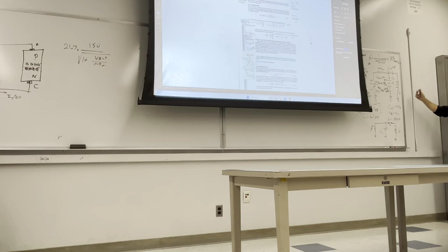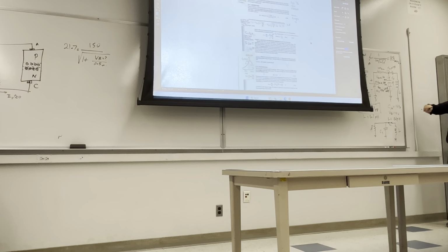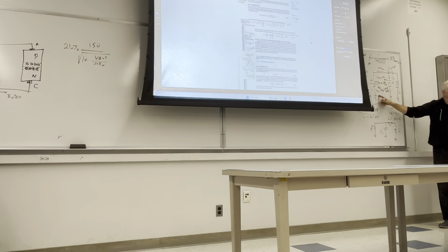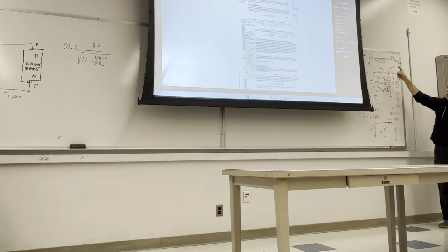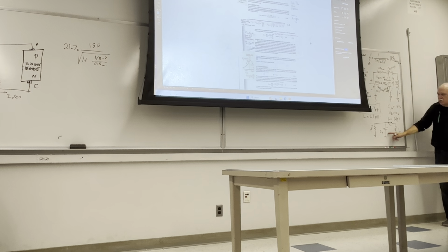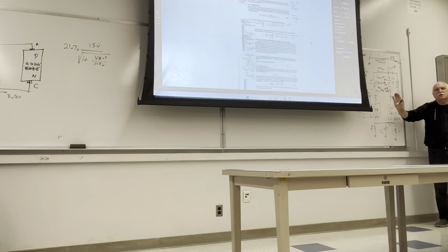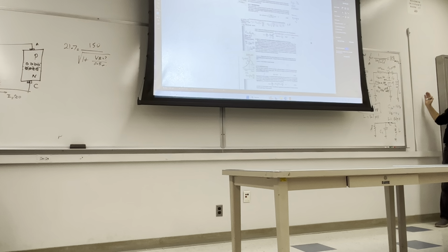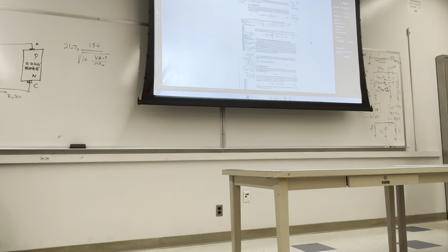We will therefore be able to scan easily, even beyond the FM radio bands, by changing this voltage anywhere from 0 all the way up to 23 volt. Then your resonant circuit will resonate between 88 megahertz all the way to 108 megahertz. That's the radio band, FM radio, 88 to 108.